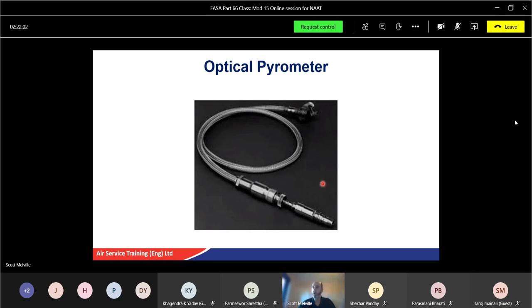Certainly the ones I used to work on, we had two of these, and they look very, very similar to there. You've got a screw head at one end, so you locate the pyrometer into the actual assembly, and you can't quite see it here, but it's a serrated type setting, so it locates it in. And then there's a threaded portion there, and this long part here would thread down and actually lock tight the pyrometer into place. Then what you would do, you would wire lock that one to the other one, and that would keep it in place as well. Okay, so that's your basic pyrometry thermocouple system.